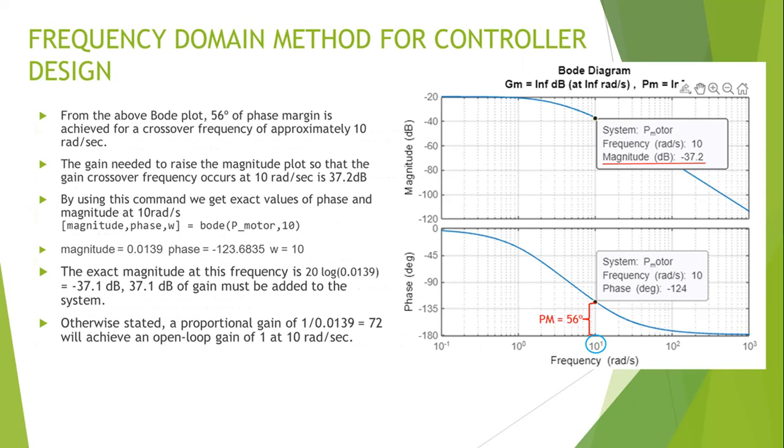From the first Bode plot, it appears that the gain margin and phase margin of the system are currently infinite, which means the system is robust and has minimal overshoot. The problem with this is that the phase margin is infinite because the magnitude plot is below 0 decibel at all frequencies. This means that the system will have trouble tracking various reference signals without excessive error. Therefore, we'd like to increase the gain of the system while still achieving enough phase margin.